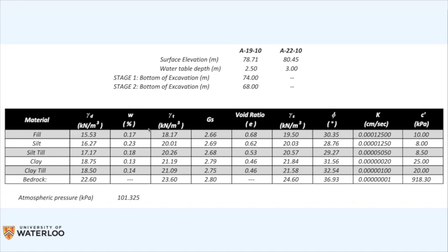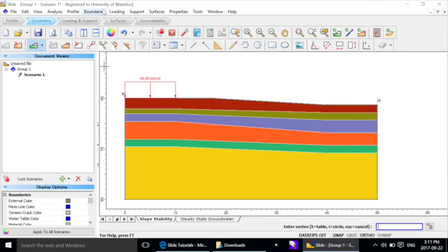So here in the software we are going to consider this new boundary, and let's say you have 10, because we know that the water table is 2.5 meters below. Assuming that the elevation of the borehole is 80, the elevation of the water table is 77.5, but the elevation of the borehole is different, okay? Just in this case, for example, I'm going to consider that, but you consider the real elevation for the borehole, okay?